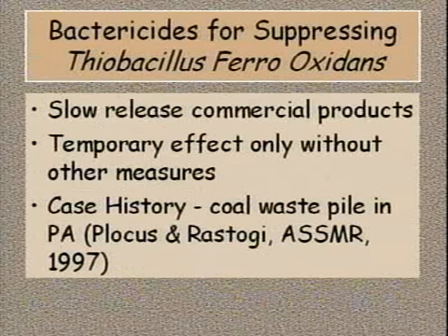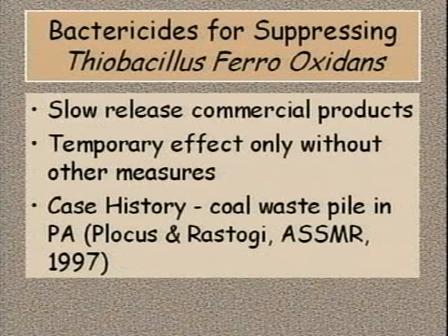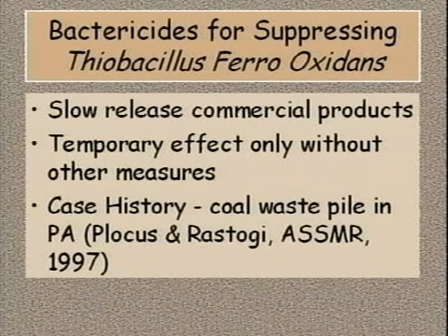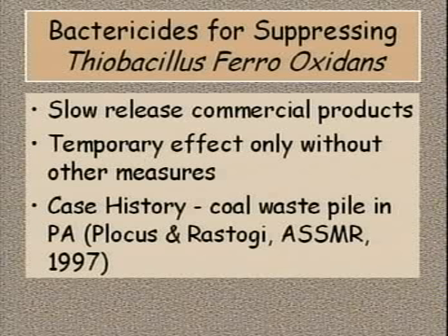Sodium lauryl sulfate is a proven bactericide for Thiobacillus ferrooxidans, but by itself it's very soluble and can be washed away pretty easily. However, there are commercially available products to deliver it in slow doses to allow nearly continuous bacterial control. But the effects aren't permanent, especially after the sodium lauryl sulfate product is depleted. So bactericide should be combined with other ARD tetrahedron disrupting techniques to get control of an ARD situation.